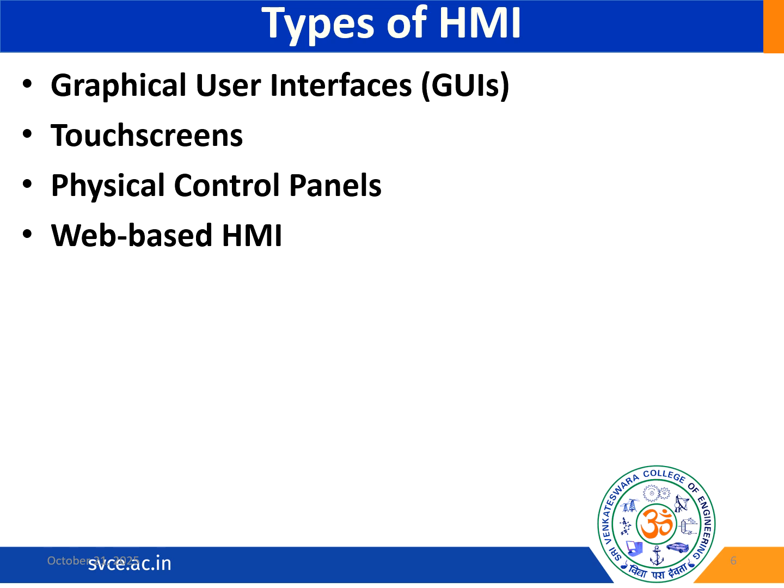So when you consider this web-based human machine interface, these types of interfaces deliver process data and control capabilities through standard web browsers. It enables operators to interact with industrial systems from virtually any device. This platform independent approach supports remote monitoring and command input without the need for specialized hardware or software installations, making it ideal for distributed operations, mobile access, and scalable control environments.